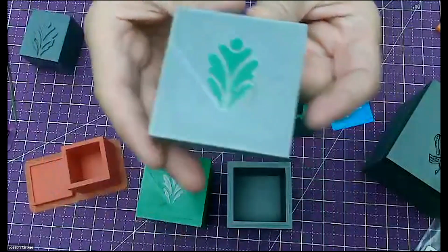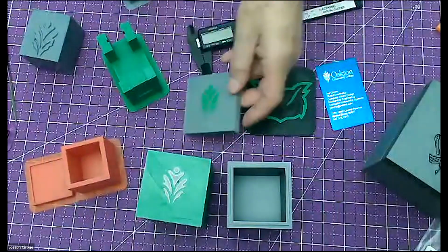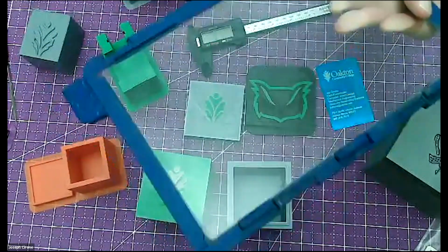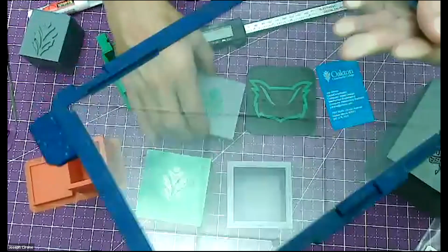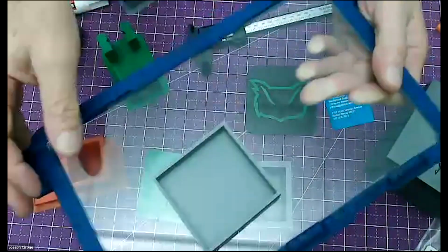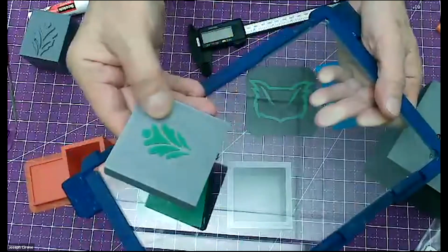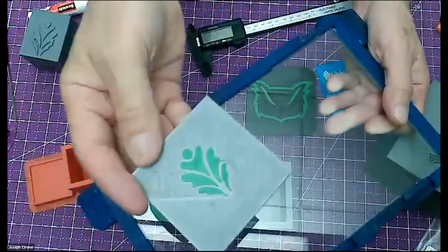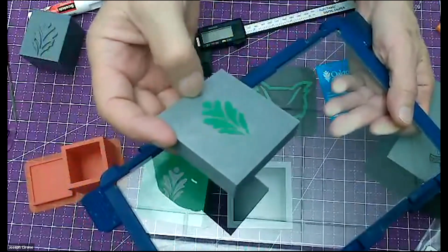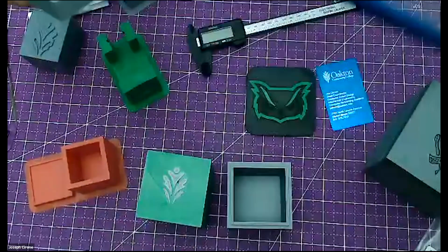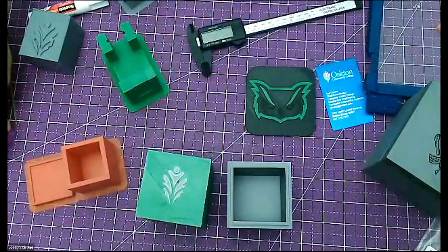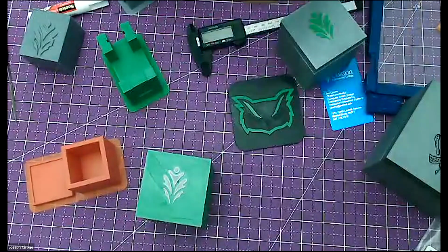I like to print these glass side down. What that means is we'll put them on the glass and set them up so that we print them face down like this, so that it's smoother. Now, depending on the printers, there's some calibration adjustments, because you can see what they call in the machine shop witness marks. You can actually see how the tool was dragging on the build plate, which can be adjusted.